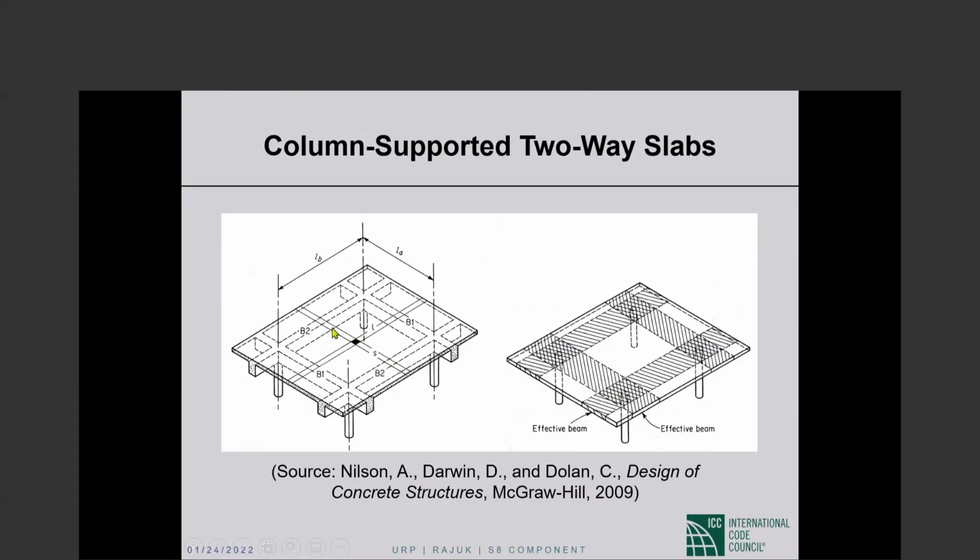Let us say the slab strips spanning in the short direction transfer 60% of the slab load, and the slab strips spanning in the long direction transfer the remaining 40% of the slab loads.